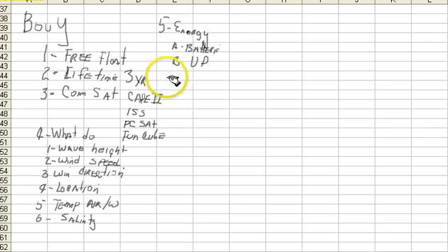The form factor, my suggestion is a 4-inch cylindrical, probably a 4-inch PVC pipe. Let's say we want it to be operational, survival at a sea state of say 30 feet. And the temperature range we'd like it to work over is say -10 to +40 degrees C.